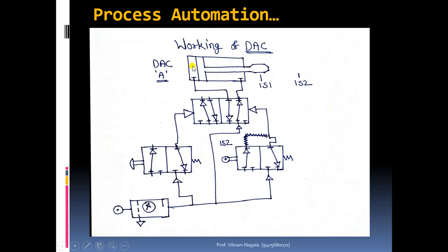At the same time, the air present on the left hand side of the piston has to come back and pass towards the input side, and it will be exhausted to the atmosphere, since the nature of this lining is to take the air from the output side to the input side.